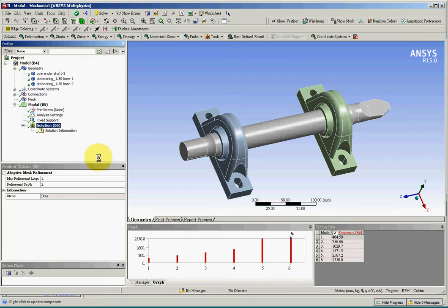This is because when a car gets old, the bolts get loosened and the rigidity or stiffness of the structure decreases, and therefore the natural frequency drops, and therefore you can hear lower frequency sounds. To fix it, theoretically at least, you can fix all the fixtures back and the noise will be gone.